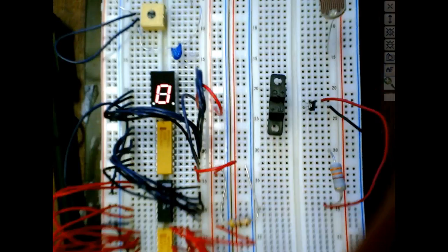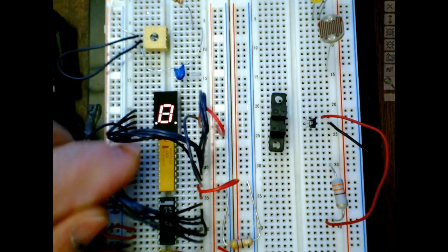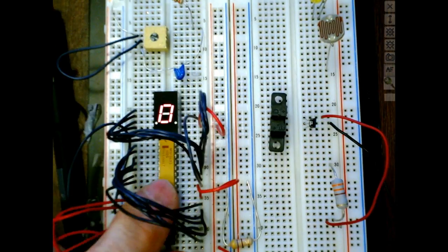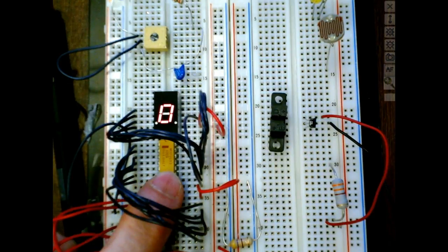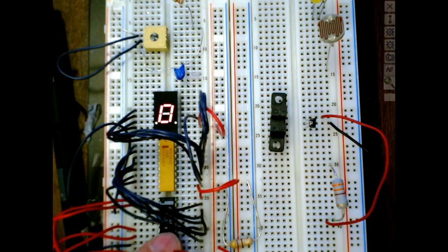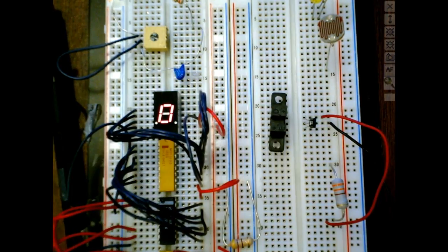So I wired this circuit up completely. So instead of using the trainer, I wired it up completely. So here's our 7-segment display up here, our common anode. Here's our resistor pack. We talked about resistor packs, right? So instead of me having to use individual resistors, I can use a pack. This is a DIP. This is not a SIP. A SIP would only have one row of pins coming out one side, and those are used predominantly as pull up or pull down resistors.